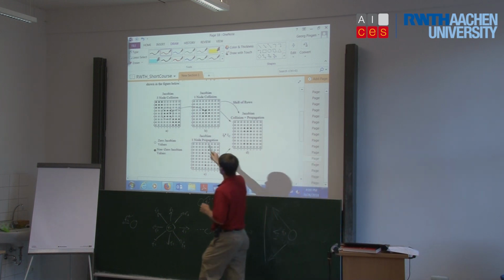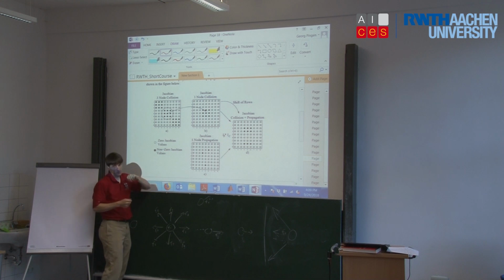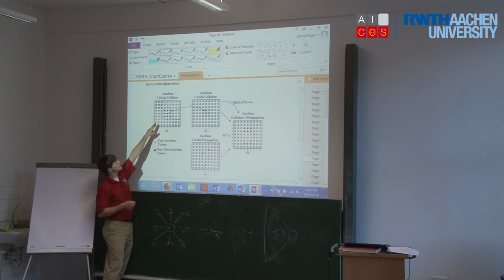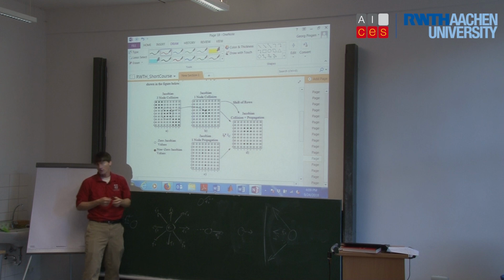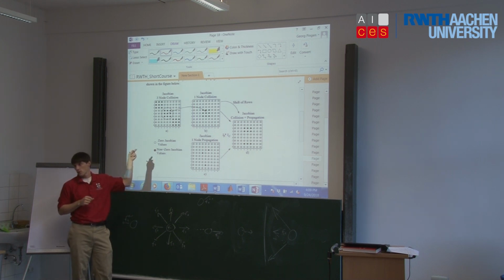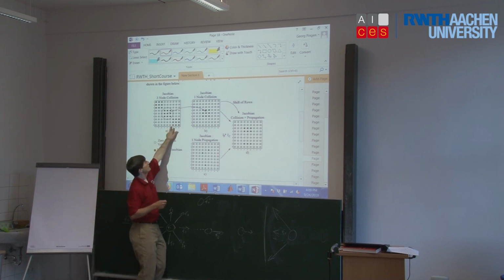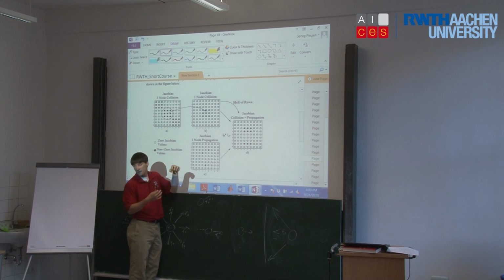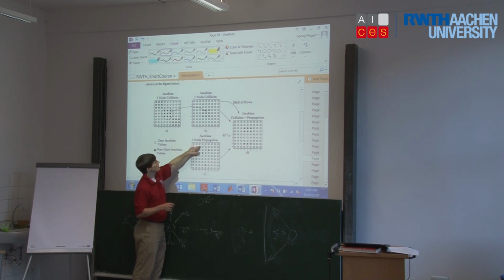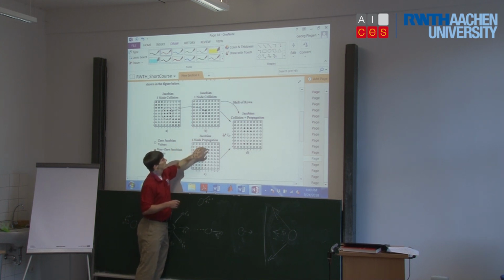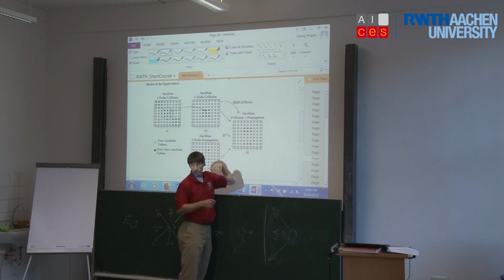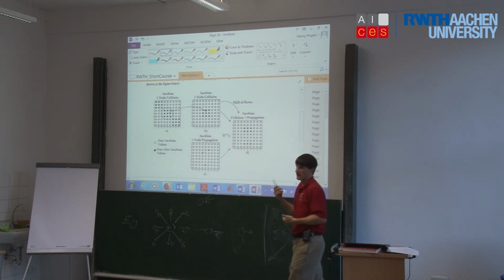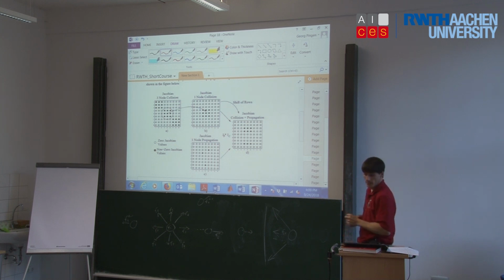So if we look just at the collision step, be a one-dimensional Lattice-Boltzmann which only has 3 functions at each node. If we had 9 functions at each node, the collision step Jacobian will give us a block diagonal structure, which would be a 9 by 9 in 2D. In 1D, it's a 3 by 3. Then the propagation step will simply shift rows in the collision Jacobian. So if we combine this, we can calculate the Jacobian of the collision step. The propagation step will shift rows in that Jacobian. And then we have our Jacobian. We need to find our inverse. And we can then proceed with our analysis.